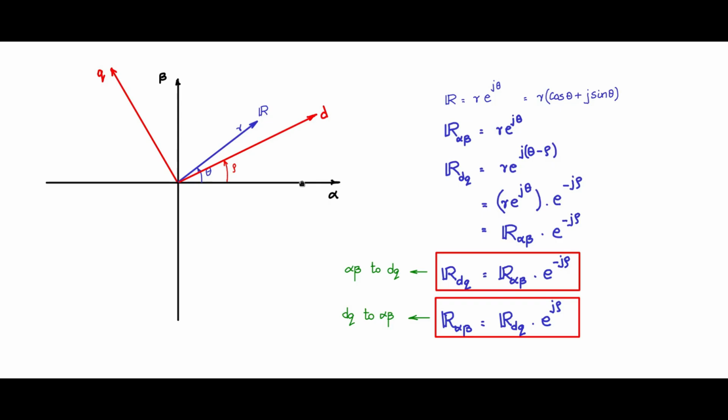So this is the principle that comes into being, and this is how we convert AC signal into DC and then do the control action here and then jump back. So all the controllers are kept in the DQ axis, the reference axis, which is rotating at omega t, or rotating at the same speed as the r vector. So this is the DQ axis theory principle. Let us consolidate with a few conversion equations, and then we can write down the block diagram.